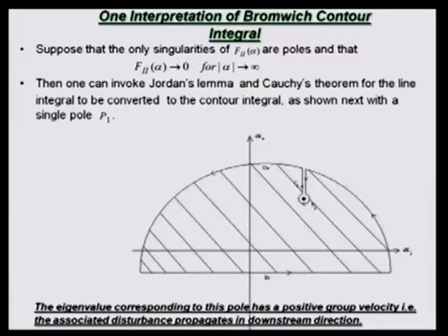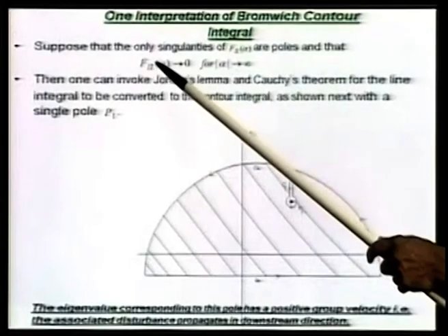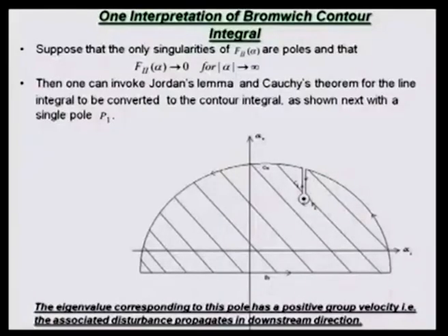So, now, what we just said: this f has a role like what we talked about, the amplitude of the disturbance stream function or the normal velocity, and then we said it will be of numerator by denominator form, and the zeros of the denominator provide you with the poles, and those poles are what? Your eigenvalues, right.